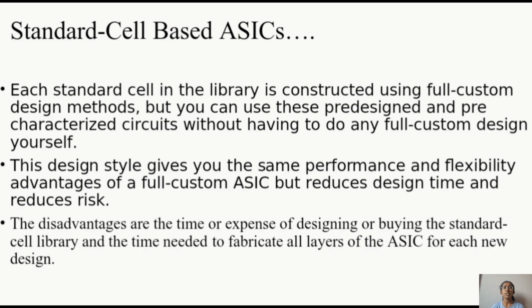In a standard cell based ASIC, each standard cell in a library is constructed using a full custom design method, but you can use this pre-designed and pre-characterized circuit without having to do any full custom design yourself. This design style gives the same performance and flexibility advantages of a full custom ASIC, but reduces design time and risk. The advantages are the time saved by using the standard cell library, and the time needed to fabricate all the layers of the ASIC for the design.